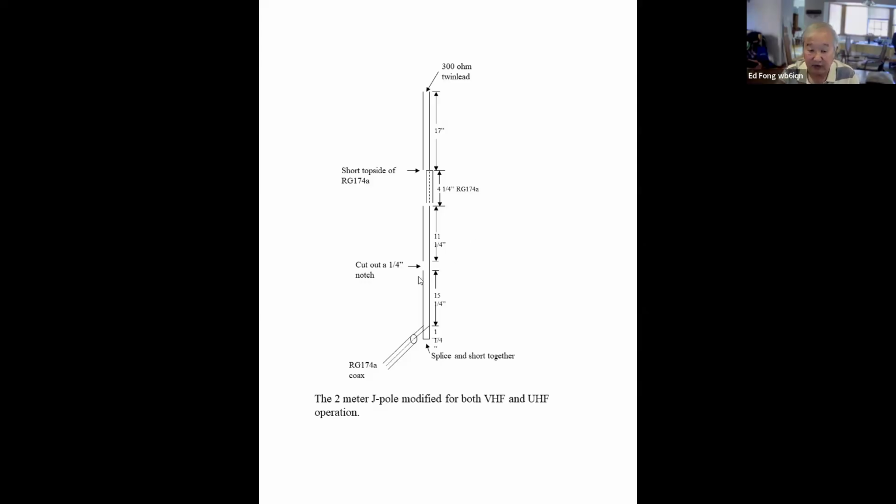So the same goes to the stub, every third harmonic. But the antenna doesn't work that way. The antenna itself, again, at UHF, will want to see a half wave, and it does, because this is short and open circuit. How do you add 220 in this? 220 is not third harmonically related. So you can't take advantage of these tricky things of playing around the third harmonic, like a G5RV antenna.